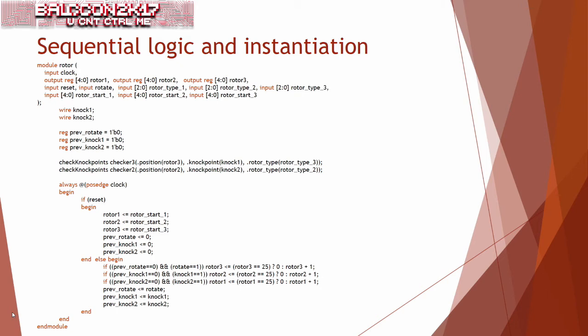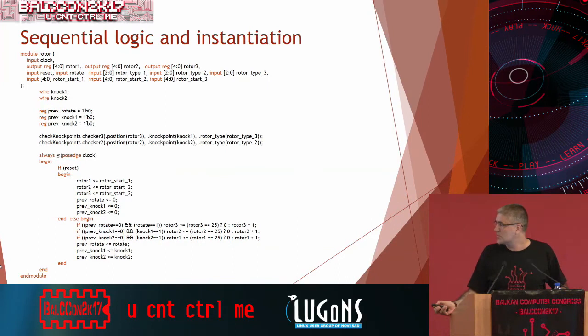And here you can do the checks. Please note that you are actually taking the current value. So if you do set something here, you still have in the next line the old version of the value. So you need to think everything is in parallel.